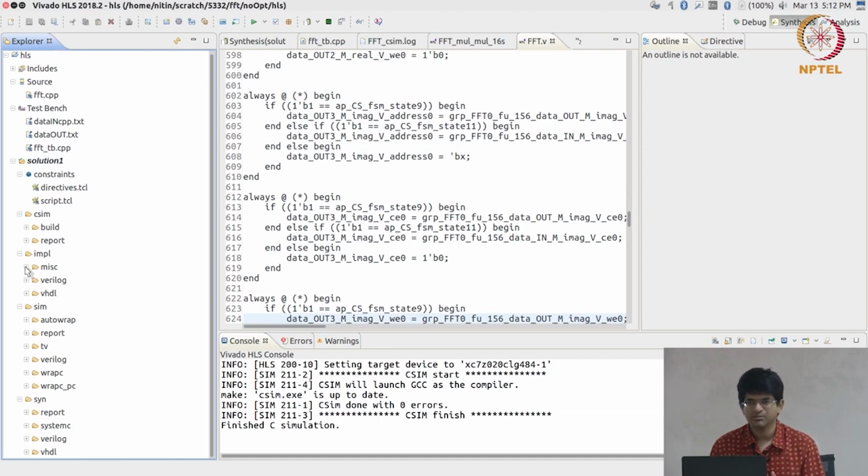So there are multiple ways of doing this kind of equivalence checking. There is one method called formal equivalence checking, which essentially says there are formal methods by which you can literally say you have the C code, these are the set of transformations that were employed by the compiler in order to convert that into Verilog, and by going through that process you can say that this line of Verilog corresponds to this input line of C, and therefore they are exactly functionally equivalent. Whatever the C code does is exactly what the Verilog code will do. In general, that is very hard to implement. We do not have such formal equivalence checking implemented over here.